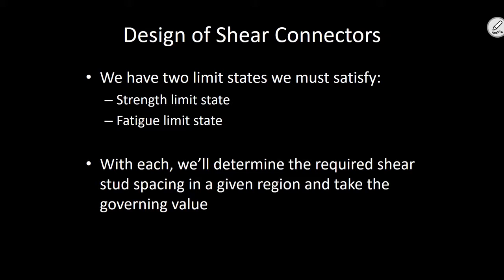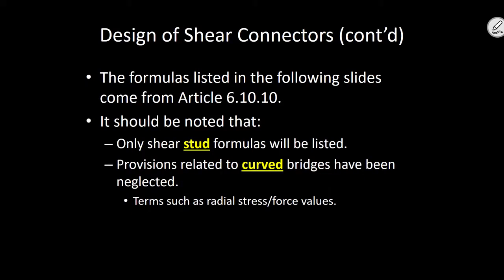And in fact, more often than not, you can probably just ignore the strength limit state for bridges and just design based off of fatigue, and you're going to be fine. Usually you'll have to have double the amount of studs, if not triple, for fatigue. That's just a rule of thumb.